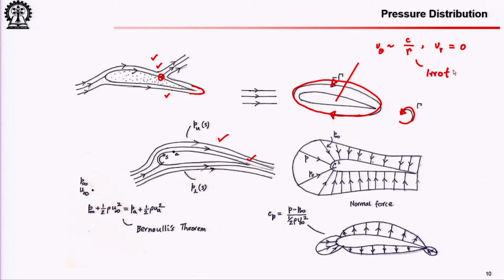So, although you think it is a bound vortex, so vorticity should be there, this is kind of a misnomer to some extent, that is, vortex does not always mean vorticity. Okay? So, here there is some singularity in the problem, but nonetheless the flow field as a whole, if you neglect that singular point at the source point at r equal to 0, is irrotational, and we will talk about it in today's lecture, or if we cannot make time today, then in the next lecture. So, this becomes an irrotational flow field.